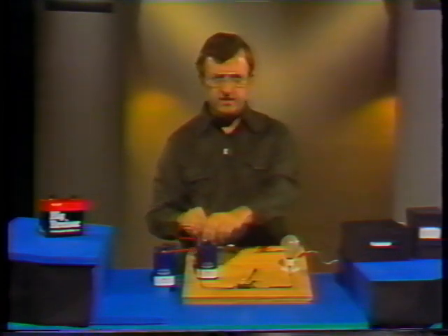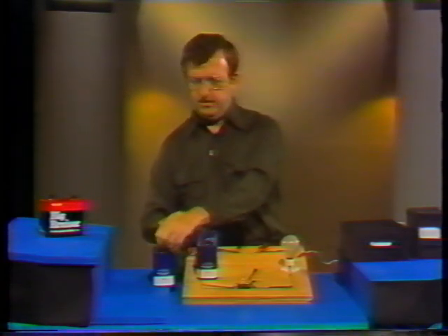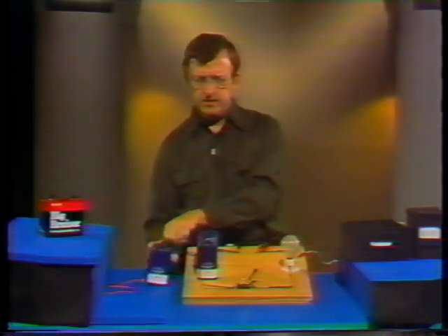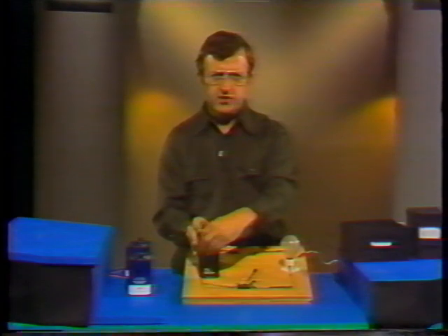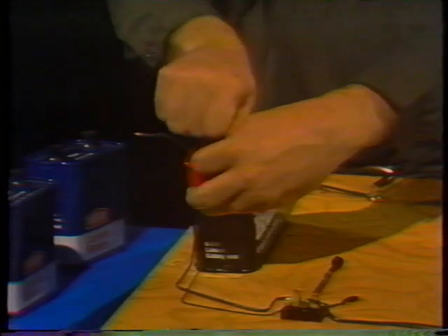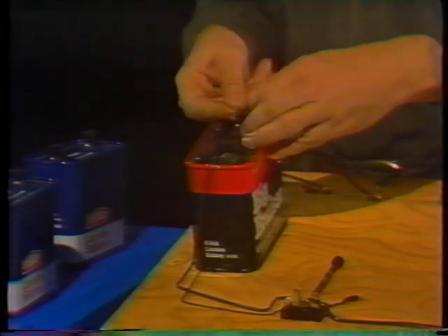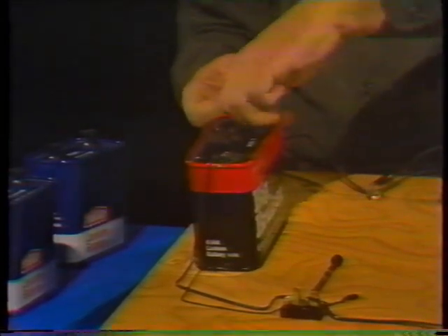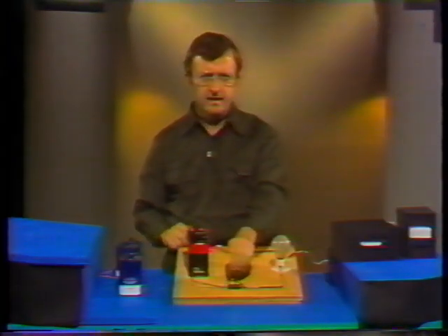We'll decrease the voltage. Now, we have already de-energized the circuit over here by opening the switch. What we're going to do is put a 6-volt battery into the circuit, and we will check it against our original reading of 2 amps. We connect the positive and the negative. The value of the resistance stays the same, just as before. I close the switch. What do we get? 1 amp. So it checks out.